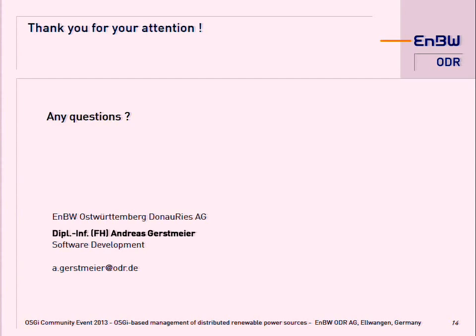I can tell you that in detail, but we just update the values if a certain level is reached. If it differs from the first value, for example if you actually have a generator value of 500 kilowatts, we just update the value in the backend if it's above 520 or below 480. So it's not much traffic influx for monitoring. No.